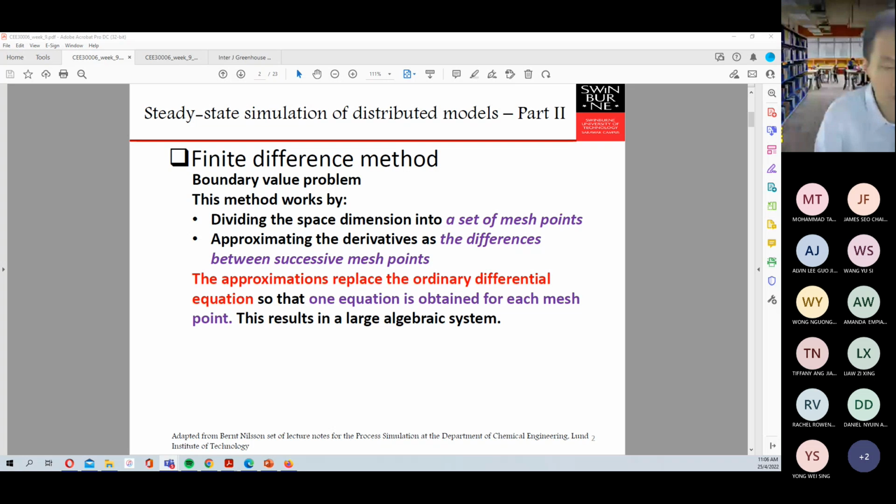After you start with the initial guess, you solve the problem, and then you see whether the value at the end matches your boundary conditions at that particular position. So essentially, it becomes a nonlinear problem where you need to use a residual, and then you can use another toolbox in MATLAB, such as fsolve, to make sure that you have a zero difference between the property value and the boundary conditions. That's basically what we showed in the MATLAB code.